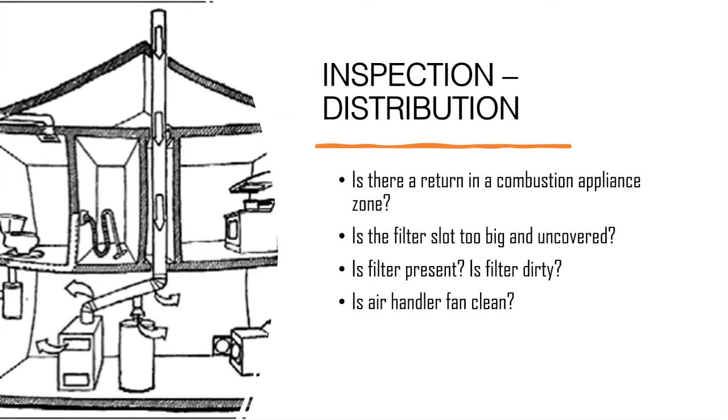Is there even a filter installed, and what condition is it in? And even see if the air handler fan is clean. If the air handler fan is dirty, the filters aren't working, and the fan can't be as effective as it should.